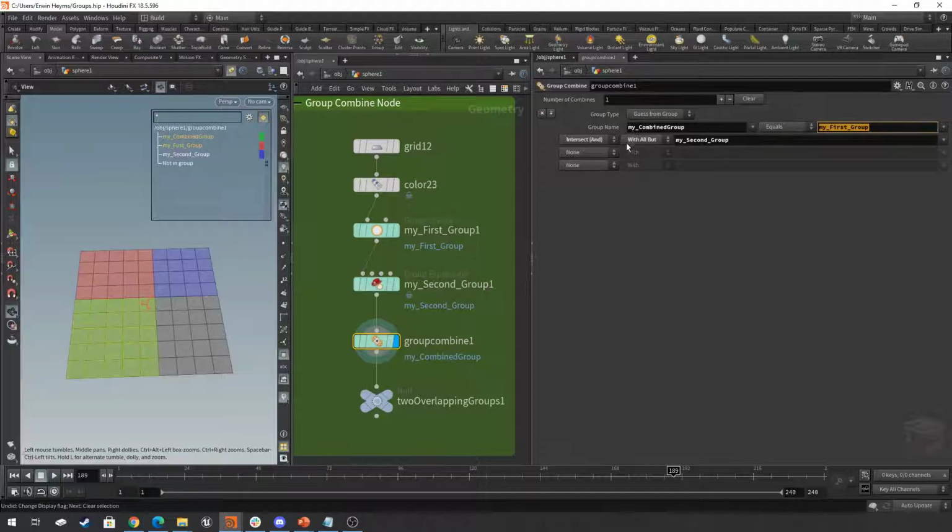So in this case I've basically inverted my selection. And of course I can say with, and then it will select this half. So in this case I'm basically just saying everything that's not in my group here, that's part of this. So this is effectively a subtraction, right? I could do this too with subtraction mode and then say with. So this allows us to combine groups together and create them into new groups or override existing groups.